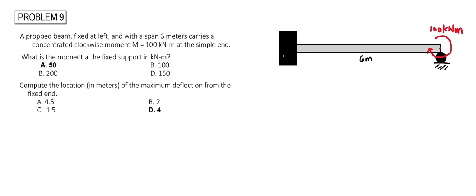Since this is a fixed end support, it will resist 3 reactions, that is a vertical force, let's call this AY, and a horizontal force, AX, and also the moment, let's call this M, that we need to solve. And the roller support will resist a force that is normal to the surface, let's call this R.